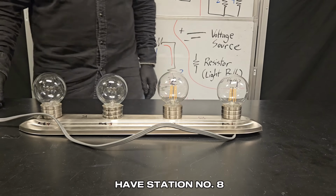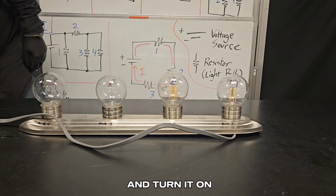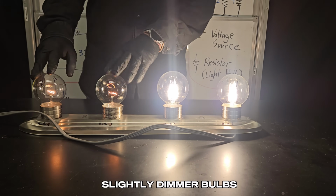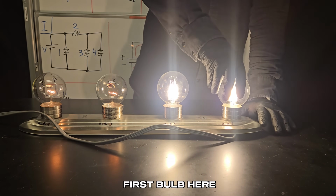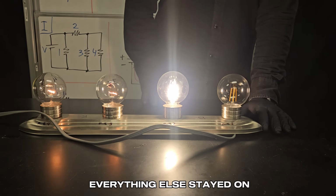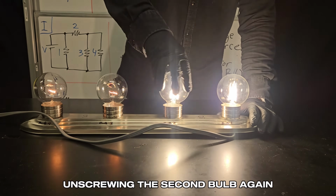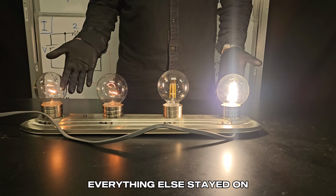Okay, so here we have station number 8. I'm going to go ahead and turn it on. And what I notice is I've got a couple of pretty bright bulbs and a couple of slightly dimmer bulbs. I'm going to unscrew the first bulb here, and I notice that everything else stayed on. Unscrewing the second bulb, again, everything else stayed on.